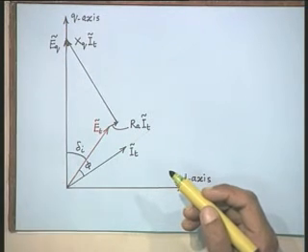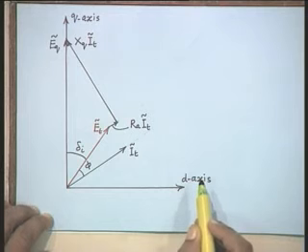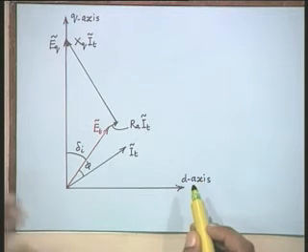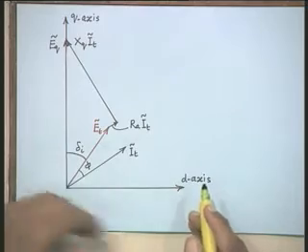And therefore, we have now established the relationship between the terminal voltage and the q axis, and once we establish this relationship, the d axis position is known, and all further computations can be done the moment we know the d, q and other quantities.